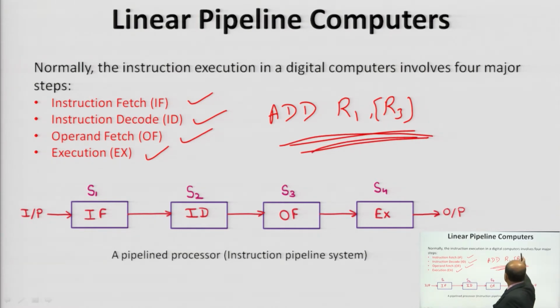Here you can see this is an instruction, and it has to be fetched from main memory, because all instructions or programs are stored in main memory. So, the processor or the system needs to fetch the instruction from main memory. That is why the instruction fetch operation is performed, and then this instruction is decoded by the instruction decoder, and accordingly various control signals are issued, as we have seen in the last class, in what step and in what sequence the control signals are generated.